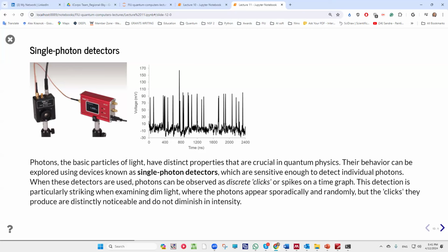You have a semiconductor crystal. You inversely bias this semiconductor crystal with some amount of voltage, basically. And when just one single photon comes to the crystal, it creates an extra net charge in the crystal.